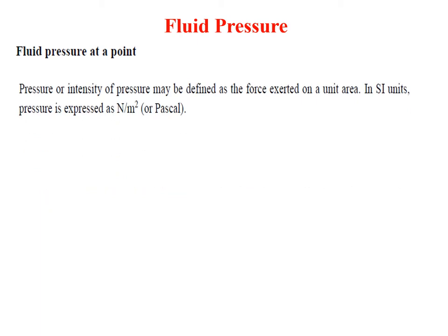You know that a fluid is capable of flowing, but when you store water, for example in a water tank or in a reservoir, the water will be at rest. Since the water is at rest and is not capable of sustaining shear stresses, we don't have any component which is tangential to the boundary.